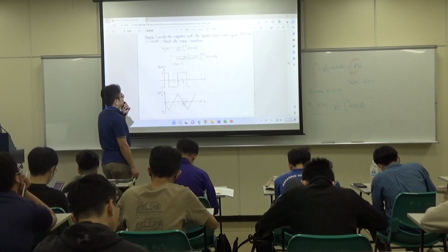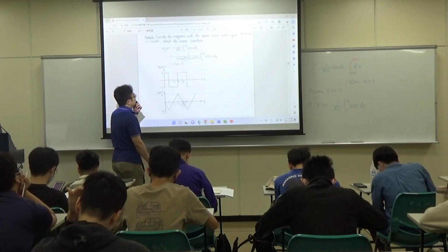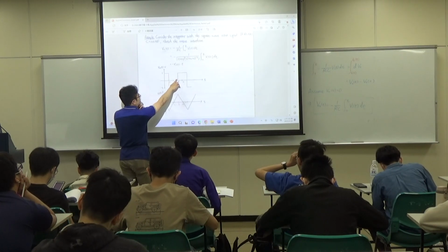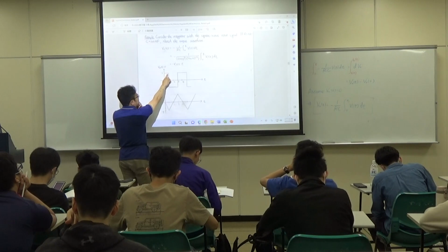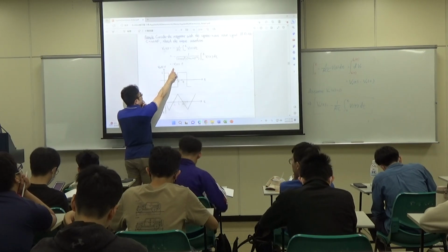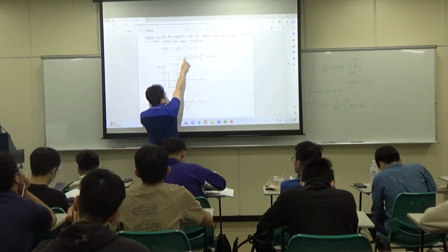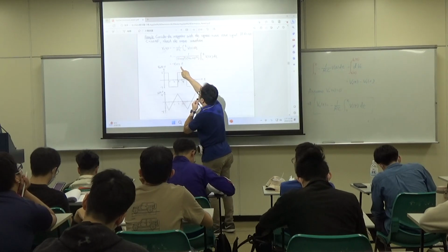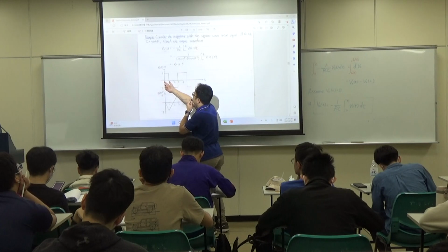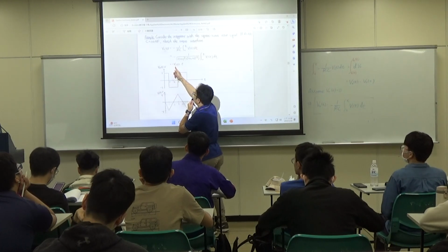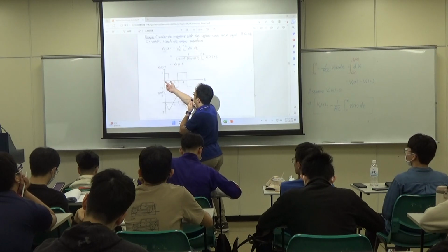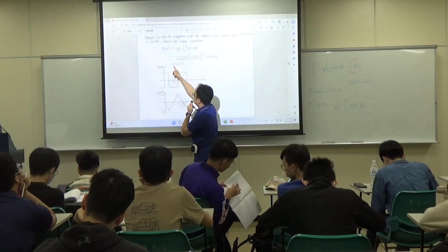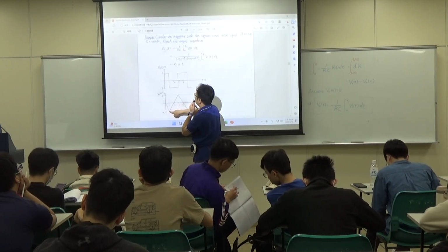So we have this. Because it's piecewise continuous, 片段连续, we need to consider the first segment, where Vi is 5. So you make the integration. First, you apply this formula, and you will have minus Vi times t. Between 0 and 1 seconds, Vi is 5, so Vo equals minus 5 times t. So it has a negative slope until it reaches minus 5.